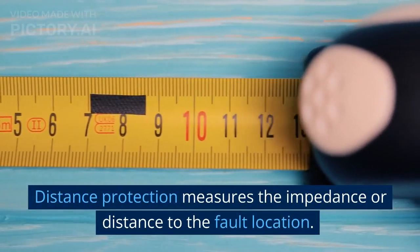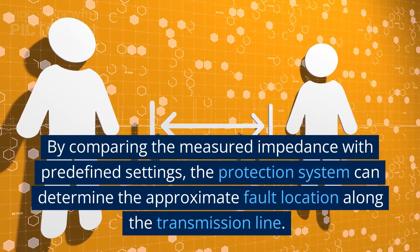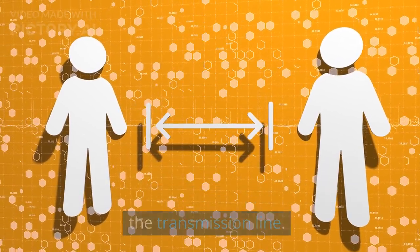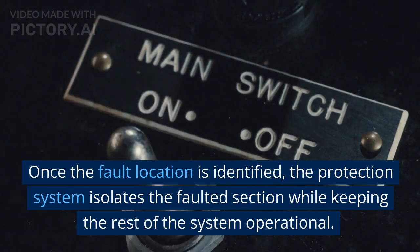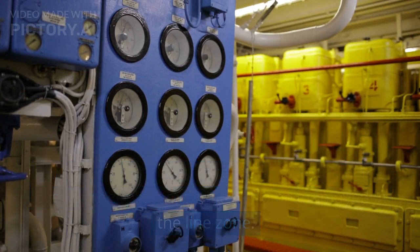Distance protection measures the impedance or distance to the fault location. By comparing the measured impedance with predefined settings, the protection system can determine the approximate fault location along the transmission line. Once the fault location is identified, the protection system isolates the faulted section while keeping the rest of the system operational. As a backup, overcurrent and directional overcurrent protection may also be employed in the line zone.